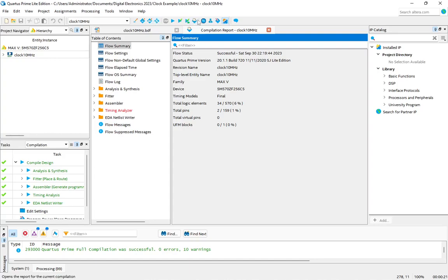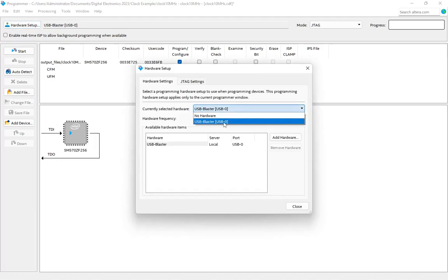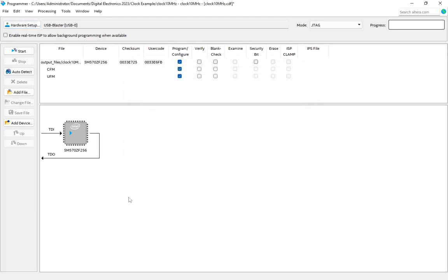Right, so after doing that, you have to go to your programmer. There's a programmer there. It says programmer, so click programmer. I'll try to send some drives so that if you want to demonstrate with your laptop, you'd be set with the drives. But it's an easy thing. So this is how you program. You have to select these, and make sure your hardware here selects the USB. After that, it is straightforward.